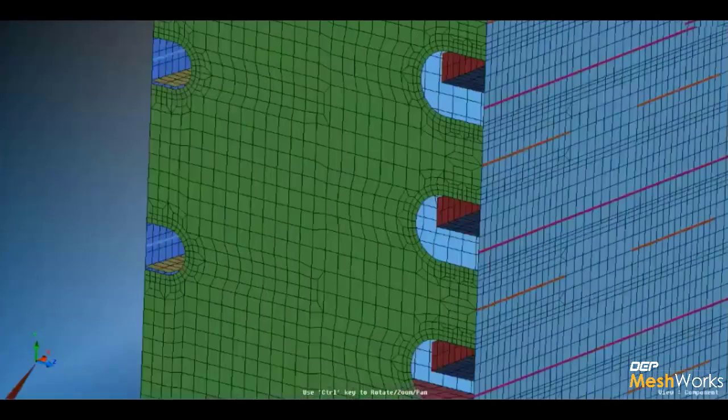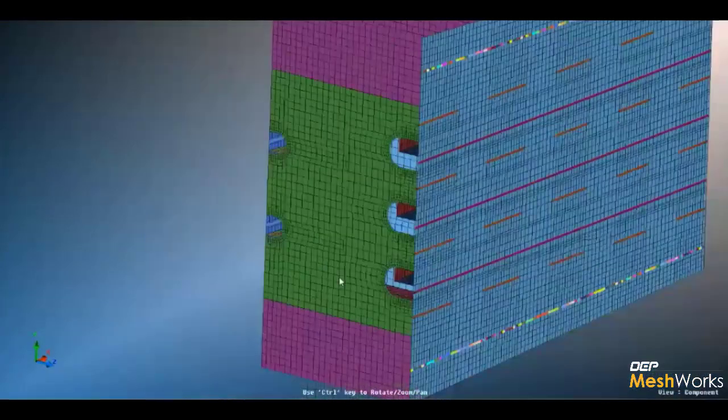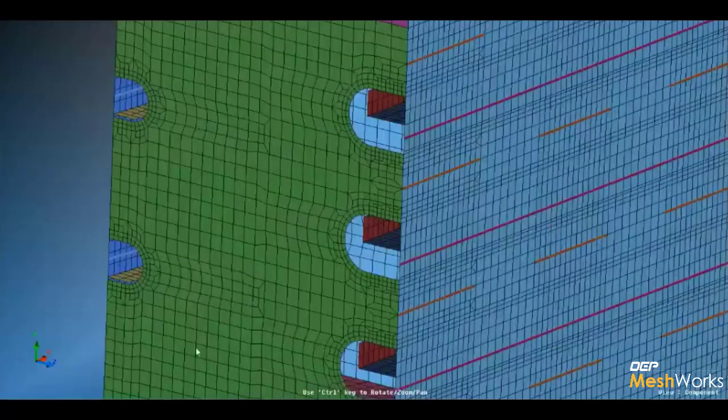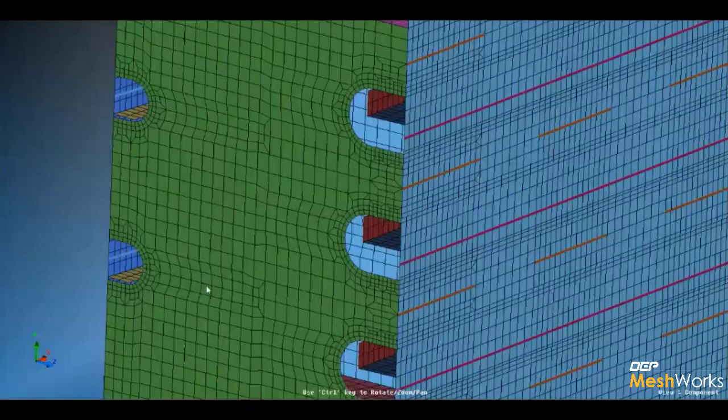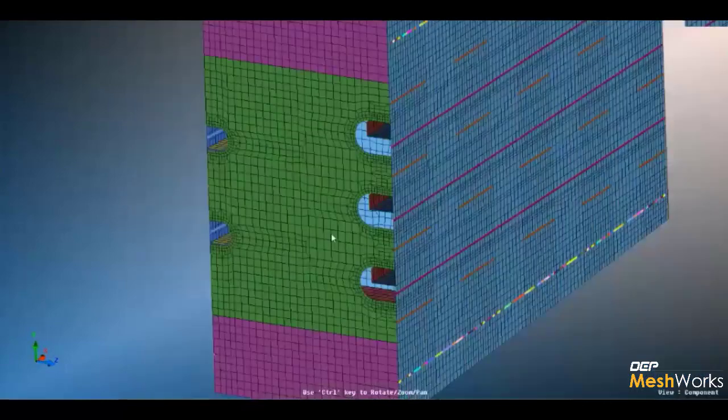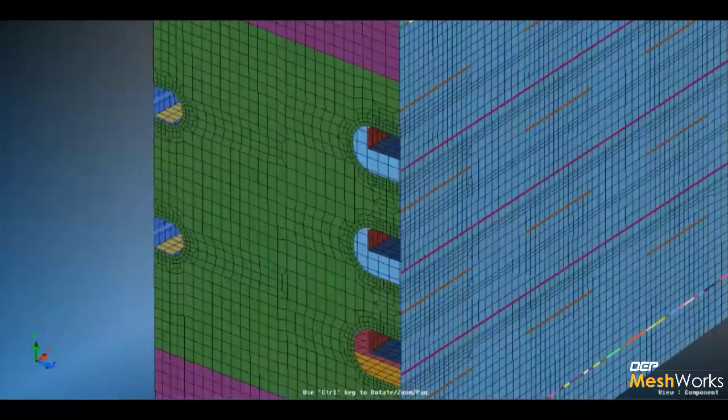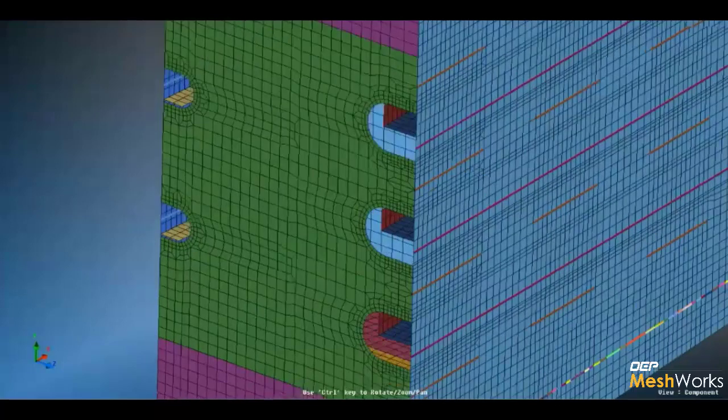So this seems to be a very small panel, but it contains a lot of process in it. Here the user is going to select only two nodes, and he will select the base component. Next, the user will specify the axis along which he wants the width of the punch hole or lightning hole, and he will specify some width for the particular lightning holes. Let's say 25. This is based on the user's input, and he will say execute.